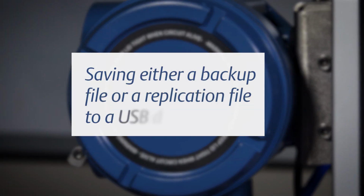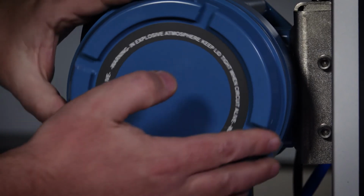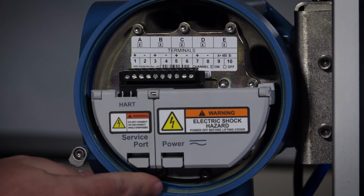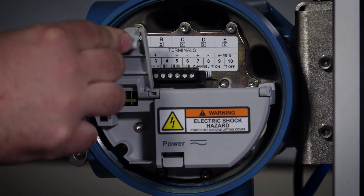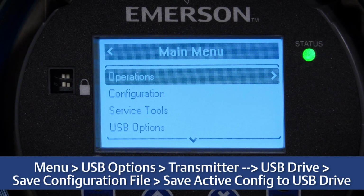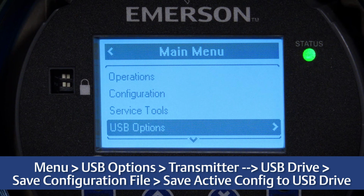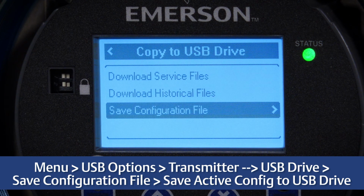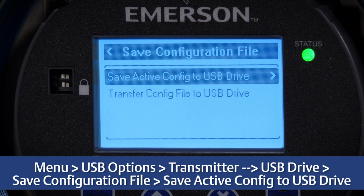To save the current configuration to a USB drive as either a backup file or a replication file, first, open the wiring compartment on the transmitter and insert a USB drive into the service port. Choose Menu, USB Options, Transmitter, USB Drive, Save Configuration File, Save Active Config to USB Drive.